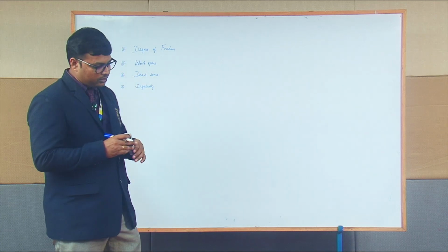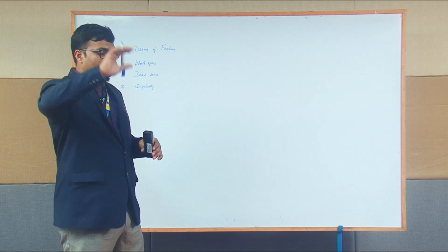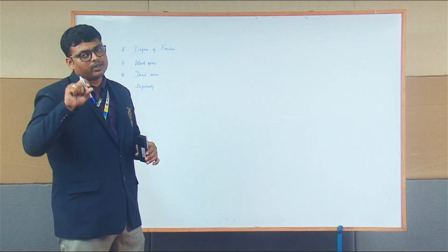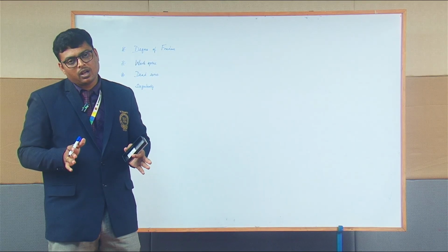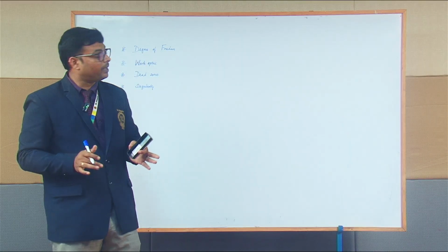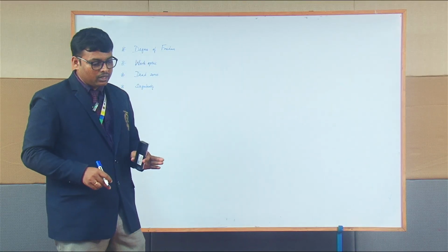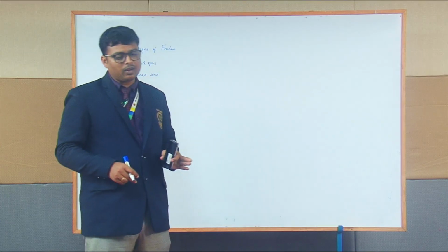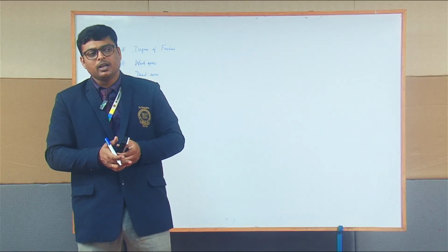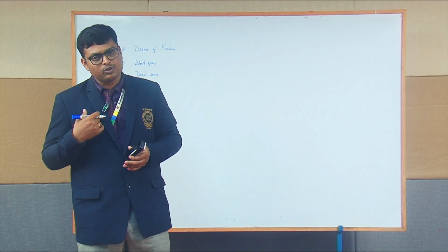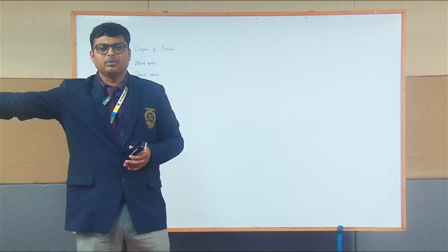So, this is for your understanding. And workspace, the workspace is the maximum reachable limit and the minimum retraction limit that a robot can possess. It will confine into a volume and that volume will be considered as workspace. And next, dead zones. So, dead zones are areas where a robot cannot move or becomes immobilized, where it can be in the inner limits, it can also be in the stretched limits, extendable limits.